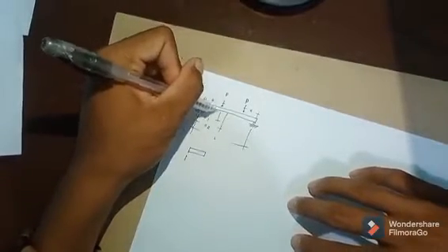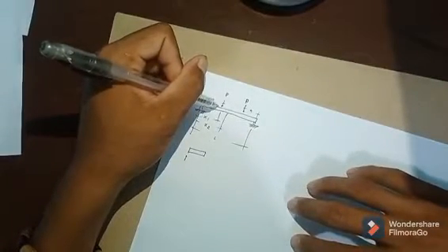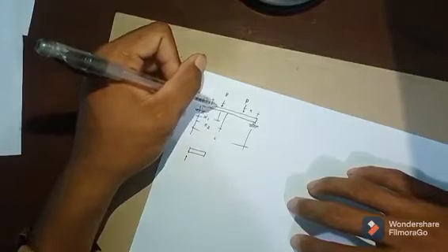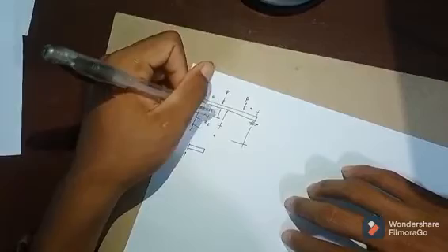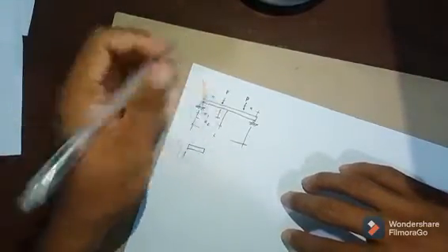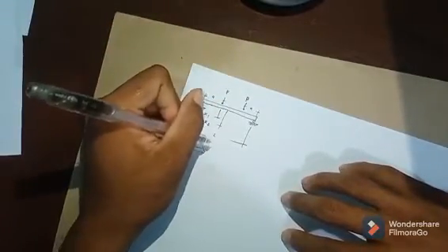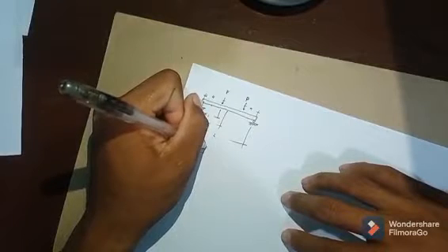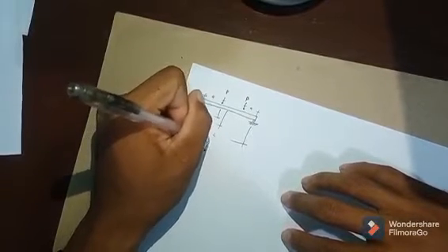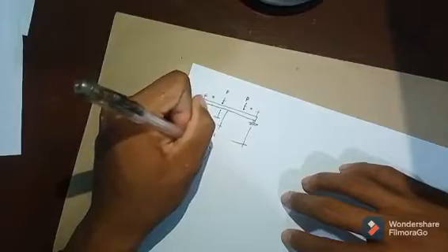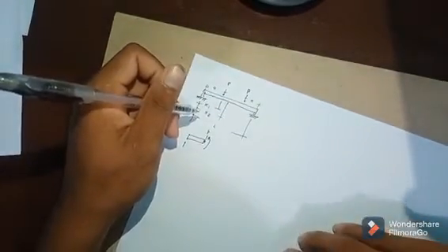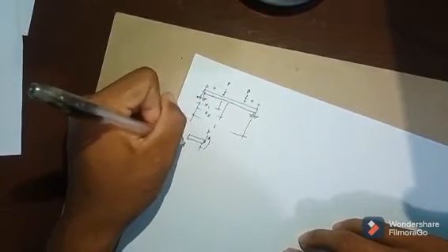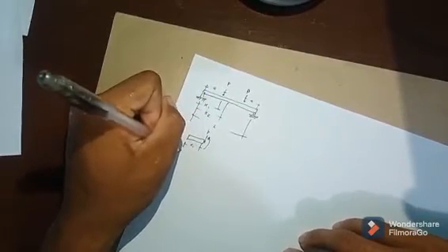If we cut the section here to find the moment and the shear in this x sub 1, we can create a positive shear, which is facing downward, and the rotation of our moment, which is counterclockwise, to have a positive moment.